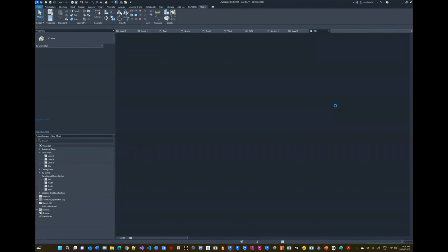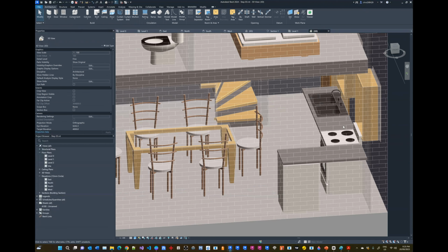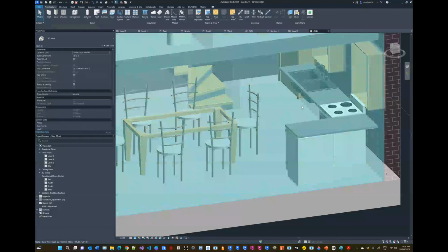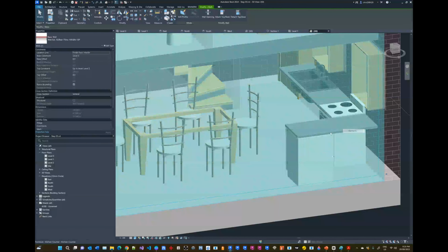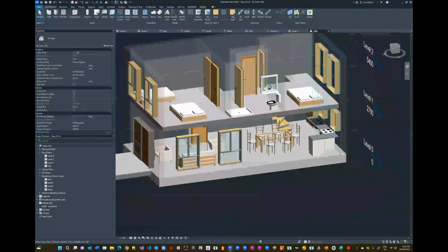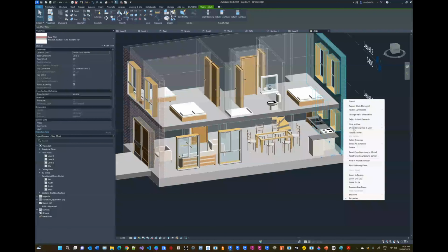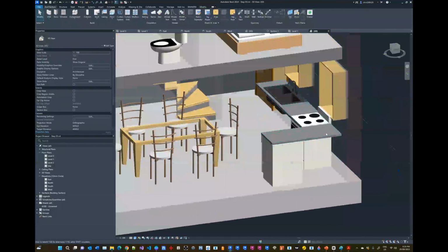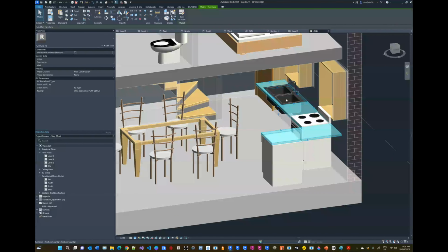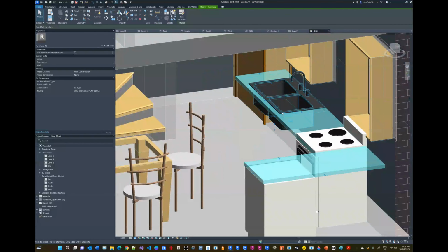One thing that I did do in my complete model is, I'm just going to hide this wall in the view so I can see what's going on. So all I did was I selected the wall, right click, and I choose hide in view elements. For this one, so that my sink doesn't intersect with the countertop that I modeled here, I actually modeled a void, right?